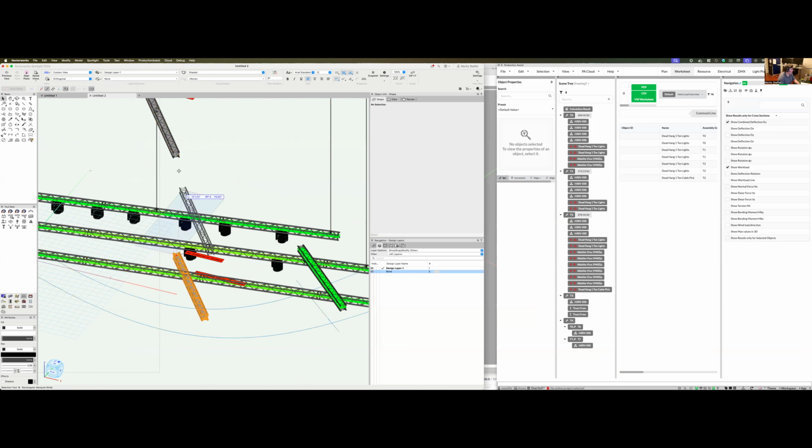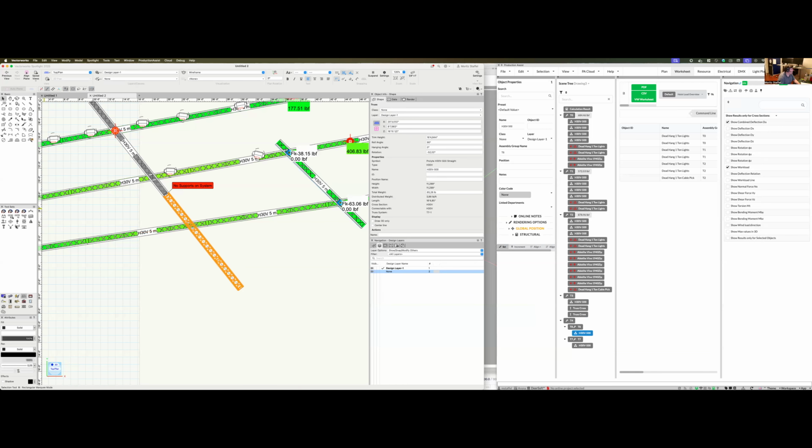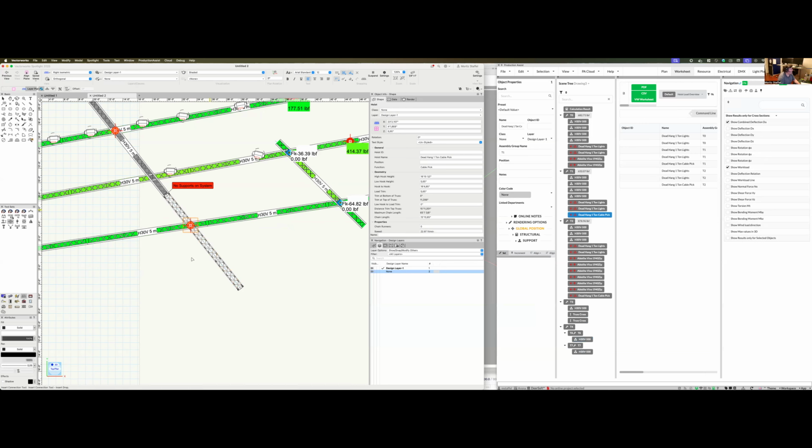One of the most critical functions in hanging system design is managing the chain shorten effect and its impact on load distribution. Chain shorten simulates the effect of adjusting a hoist's chain length, showing how even a few centimeters of change can shift load distribution between hoists. For example, shortening the chain on one hoist might reduce the load on a central hoist while increasing the load on the outer ones. Production Assist recalculates these effects instantly, updating the web palette and your drawing with precise numbers.